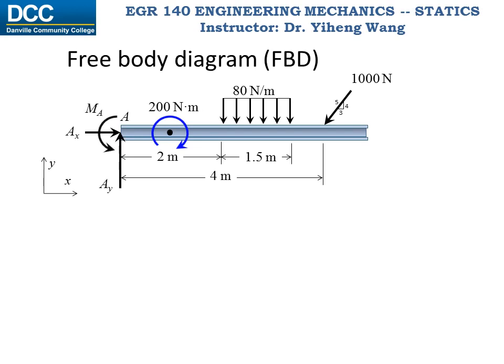Since this is a 2D problem, all motions can only occur within the xy plane, therefore there cannot be any other type of motion, and the wall will not provide any other type of support reactions. Now the free body diagram is complete, and we have exactly three unknowns, Ax, Ay, and Ma. Therefore, we can write the three equilibrium equations to solve for all of them.